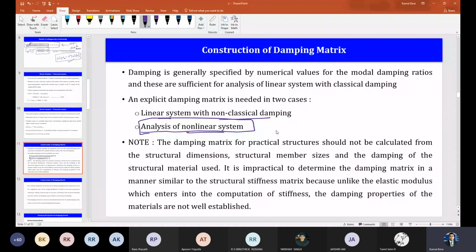You see, okay. So for linear system, the modal analysis or mode superposition, that term, right? Just keep in your mind. So that is only valid if the system is linear, right? So what we are basically doing, we are solving n simultaneous equations, we are uncoupling it, right? During that uncoupling, first of all, we are assuming that x(t) equals u1 eta 1 plus u2 eta 2 plus u3. That is one superposition of the response from all the modes. And then also,